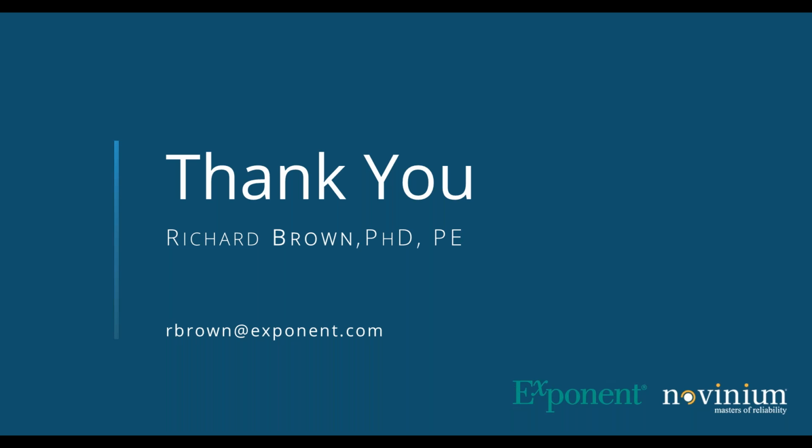All right, thank you. It looks like we have one more question we can do. What diagnostic test data did you factor in for your failure model? No diagnostic test data at all. This was all just based on historical failure data. They did not do any tan delta testing or any partial discharge testing, nothing like this. It was all just based on actual cable that failed in the field, that faulted in the field.